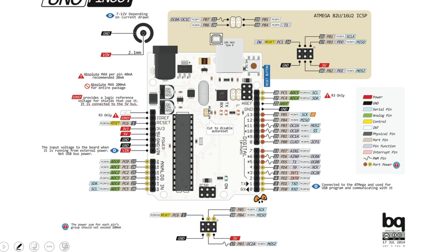And when you go about using them, the main thing that you would have to figure out is using a pinout diagram to figure out what each pin means, what things you can connect to these pins, which are the power inputs, which are the power outputs, which are the digital inputs, which are the analog inputs. So from a course point of view, we are not going into details about each of the various microcontroller boards that you can come across. That you will have to study on your own, and you can easily find these pinout diagrams online and learn about those. But we are just covering the general principles here.